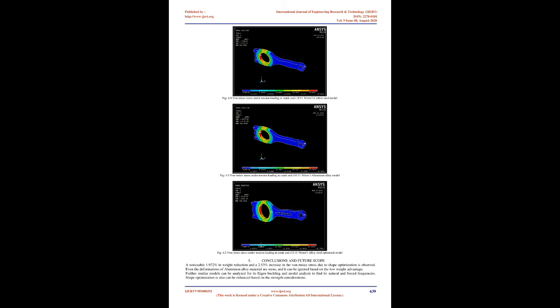At the crank end, 10.11 MPa in tension and 20.67 MPa in compression is taken, while the other end is in fixed boundary condition. Similarly, at the pin end, 22.24 MPa in tension and 20.17 MPa in compression is taken, and the other end is in fixed boundary condition.